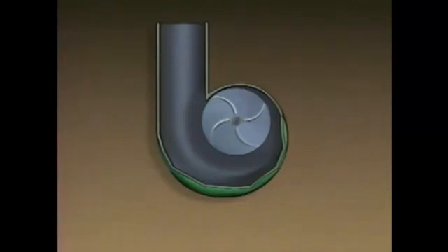The compressor's main internal components are an impeller and a volute. The volute is a continually widening chamber that is connected to a gas discharge line. The impeller rotates during operation. Gas that enters the compressor at the center of the impeller is swept up by vanes on the impeller and moved outward by centrifugal force. This action increases the velocity of the gas.